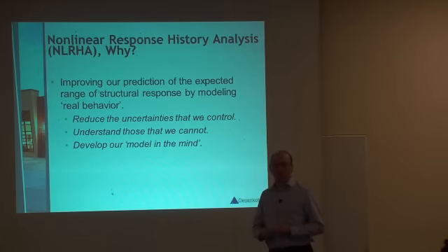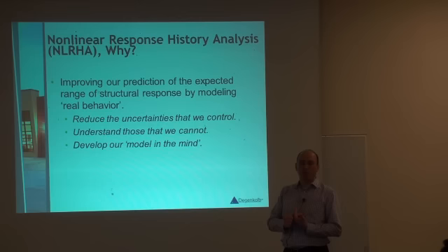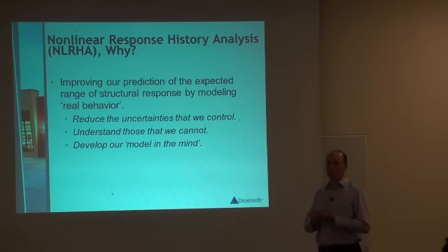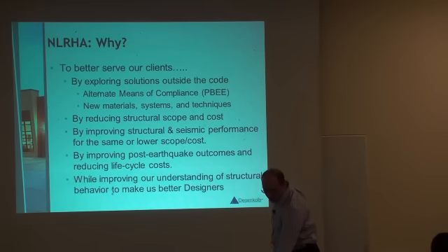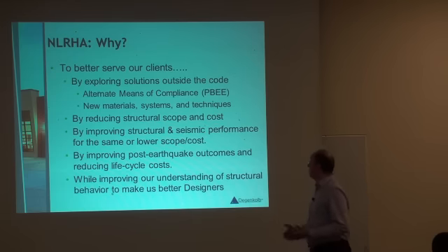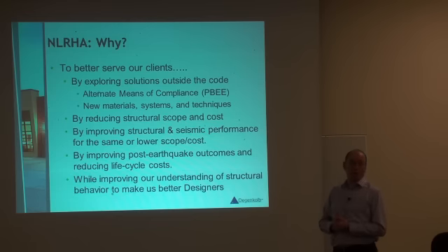And one of the reasons we do response history analysis is, in many cases, we want to reduce some of the uncertainties. We want to reduce some of the conservatism in the code. And so we model the structure to the nonlinear range. Other reasons is we want to better serve our clients, especially on existing buildings.